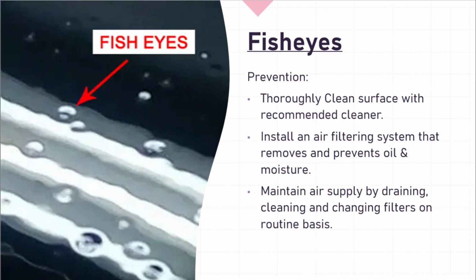To prevent fisheyes from occurring, thoroughly clean surface with recommended cleaner. Install an air filtering system that removes and prevents oil and moisture. Maintain air supply by draining, cleaning, and changing filter on routine basis.